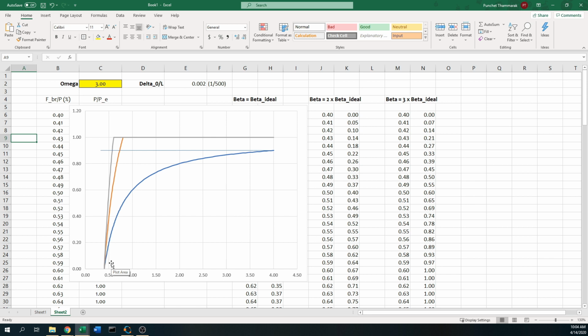The thing is that when you put the large cross section, you have 2 things at the same time. So you will have the large stiffness and the large force carrying capacity, right? So there will be some optimal number somewhere around 2, 3. That is just good, because if you provide more and more stiffness, then the bracing force will be less and less, but your capacity is proportional to the stiffness, right? So you have more than enough capacity, but the bracing force is very small. So you will just find the point that is a good and optimal point for the design, and the design code will recommend you some number, and we are going to talk about the design code point of view later. It might be tomorrow.